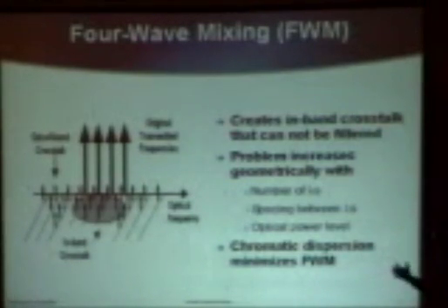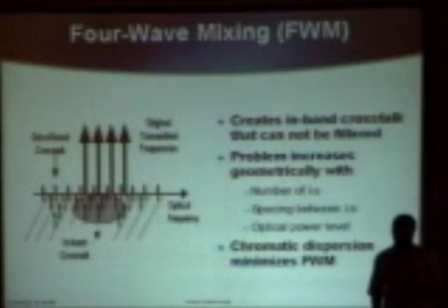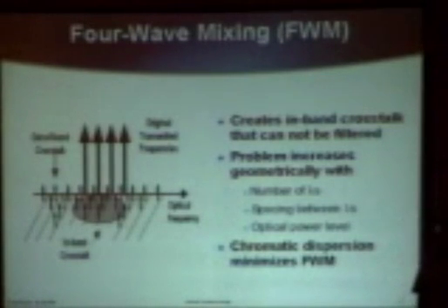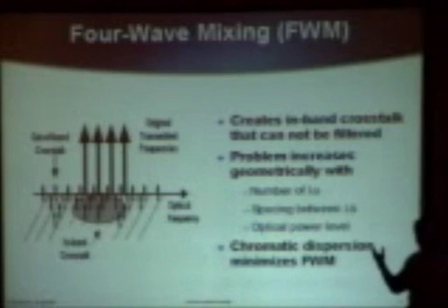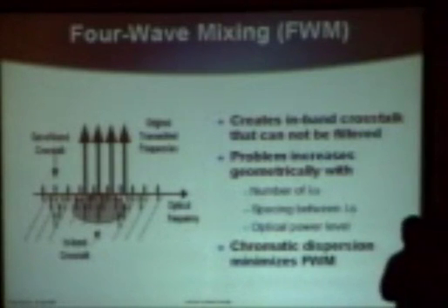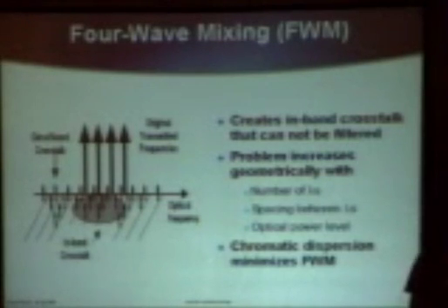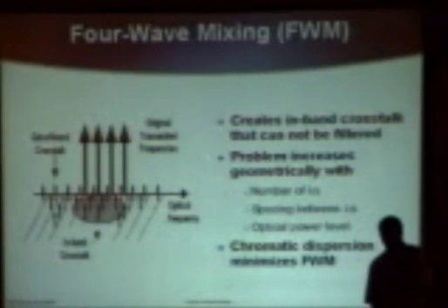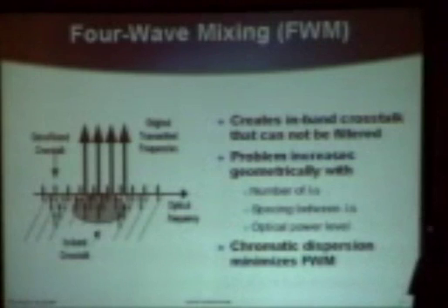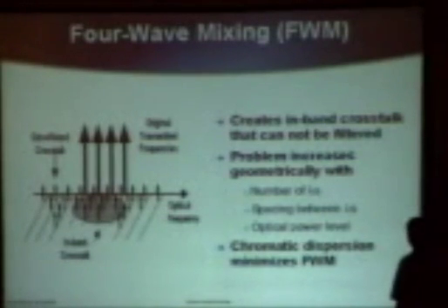So this is the give and take that the people that design WDM systems have to go through constantly. If we increase the bit rate, we have more problems with chromatic dispersion. If we lower our dispersion on the fiber to correct for that problem, we cause four-wave mixing problems, and it's a careful balancing act going back and forth between these three simple nonlinearities and a whole host of others that are carefully balanced at the analog transmission level to make it all work.